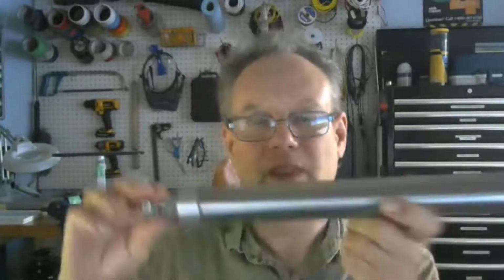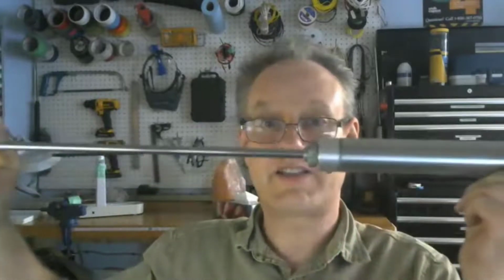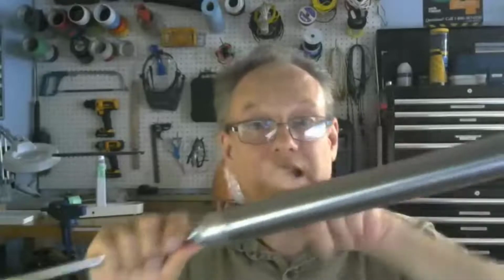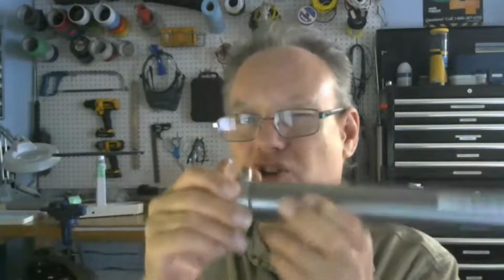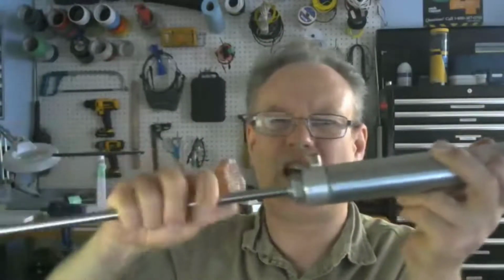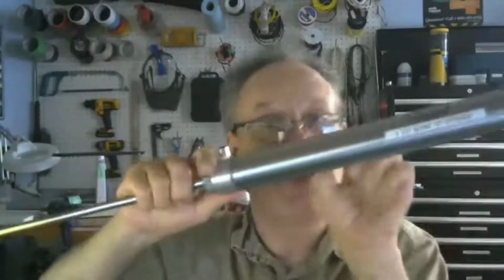But that's only during extension. Once it gets to the end, the volume in here is pressurized air equal to system pressure. The actual pressure drop is only during extension and maybe a few milliseconds after, because then it pressurizes really quickly.